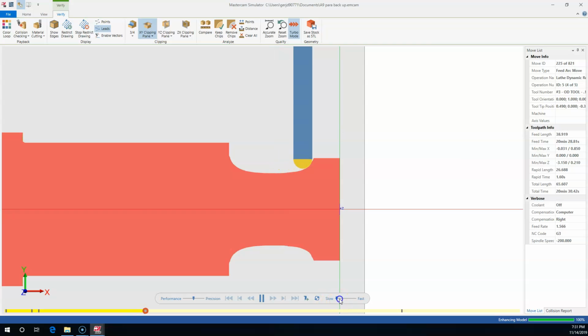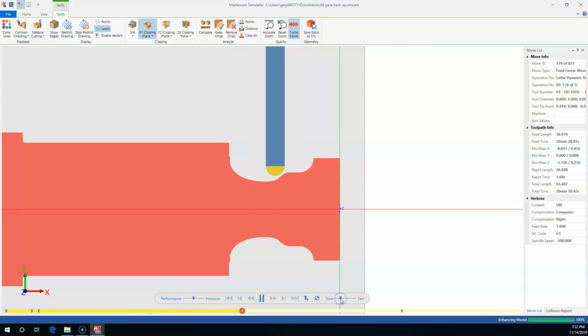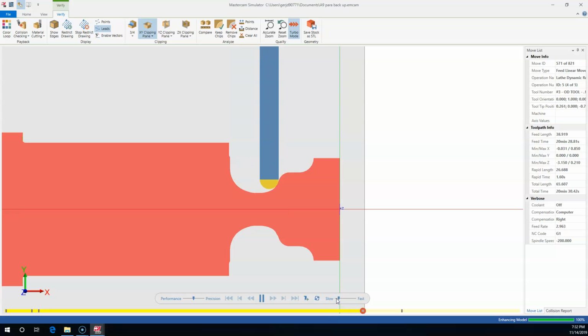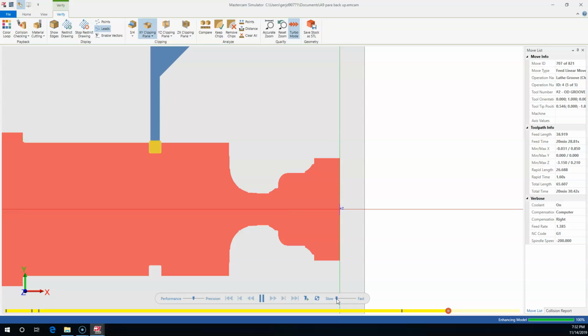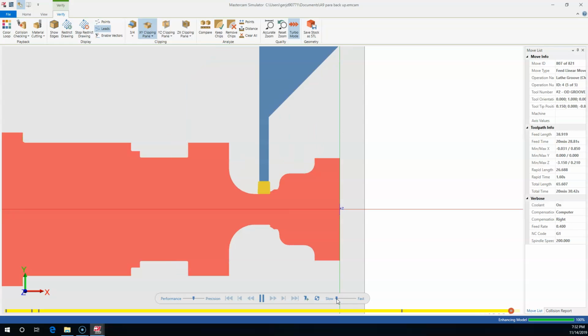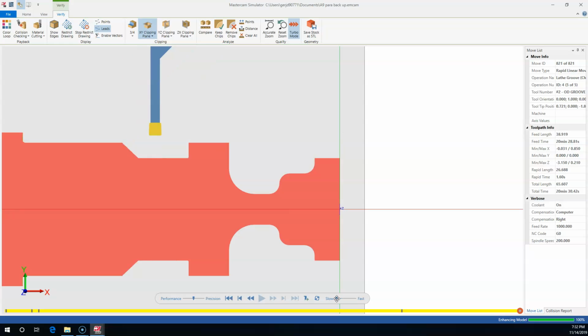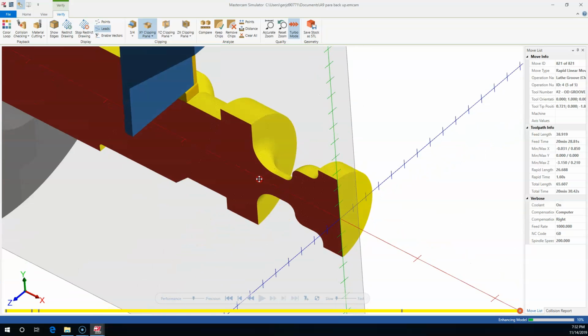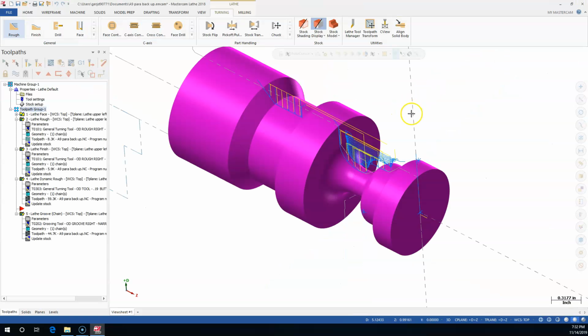And that one can go a little faster because we're going to be here for a while. Alright, and then the grooving, which is the one I really wanted to see. So it's kind of coming in. Oh, that didn't clean up as well as I expected. So it's going to do a little bit better on the non-curvy surfaces. There we go. So it comes in. That's looking better. And so apparently the dynamic left a little more material than I expected anyway. So we're closer. That's going to require a little more tweaking of the operations, but that gives us a